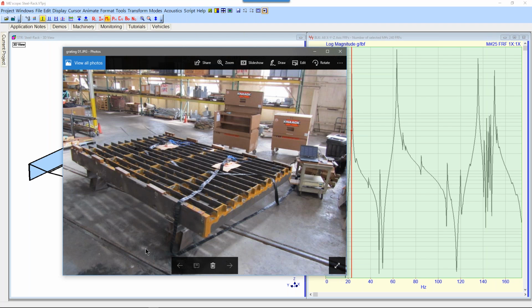And it was impact tested, and it was impacted in 3 different directions from one of the corners. So once that is done with a fixed impact, or a fixed input point, that would be the reference, and it was impacted in the horizontal X, Y, and then vertical Z direction. So 3 sets of data really were taken. 3 different impact tests done with all the accelerometers in place, basically impacted from the X direction, the Y direction, and the Z. Let's take a look at those.